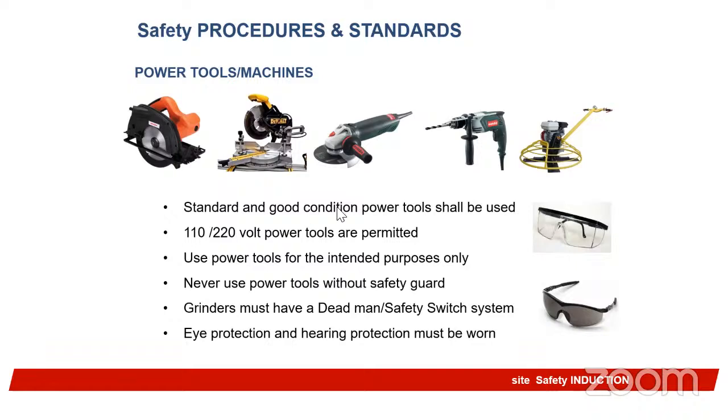So standard and good condition power tools should be used, and they should be properly inspected. Tool standard: 110 to 220 volts power tools are permitted. You should talk about the voltage of the tools they are bringing into site. That's why tool inspection is also very important, because when they bring a tool with higher voltage, and the electrical installation in the facility is just for 220, and someone brings 330, I think it can have an effect on the electrical connection. So these are also part of the stuff that you should talk about.